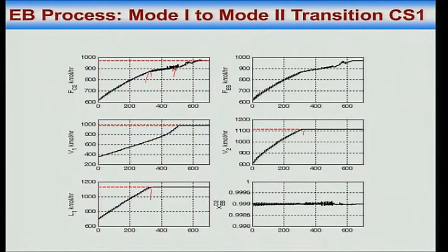In spite of that, I am still able to jack up the throughput by playing with those two unconstrained degrees of freedom, 112 kilomoles an hour to 230 kilomoles an hour, and benzene impurity from 0.04% to 0.09% or 0.09% to 0.04%. Does that make sense? So I am getting an increase in throughput, and I am able to get to whatever was my maximum capacity, 970 kilomoles an hour. Okay.